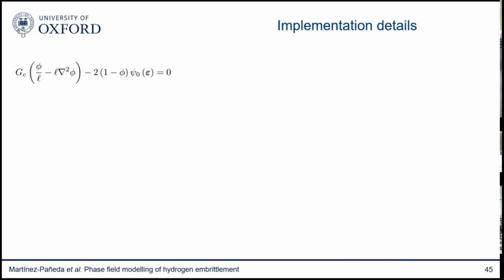How different are those models from the standard finite element code that I use in ANSYS or Abaqus and so on? It is pretty similar. The only thing that you need is an additional degree of freedom. So in addition to the displacement, you solve for the phase field. So it's an additional equation. But this is actually straightforward to implement. The first time I heard about phase field was in 2016, and I went back home and I implemented it the morning afterwards. So it was really straightforward.